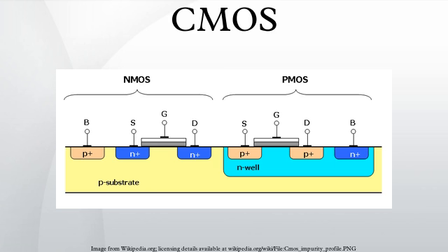Using high-K dielectrics instead of silicon dioxide, the conventional gate dielectric, allows similar device performance but with a thicker gate insulator, thus avoiding this current. Leakage power reduction using new material and system designs is critical to sustaining scaling of CMOS.